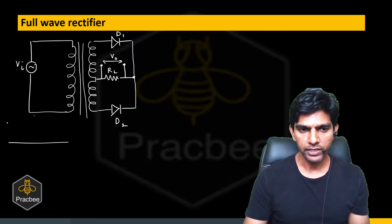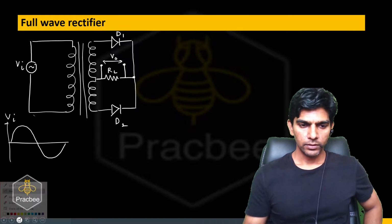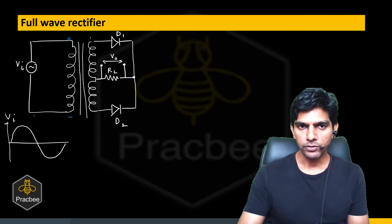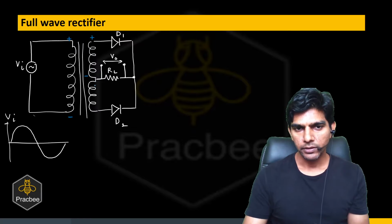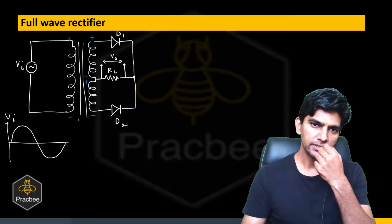Again, here what is happening? So we have a sinusoidally varying input voltage. This is input voltage, and in the positive half cycle, the top side of the primary will be at high potential and the bottom will be at low potential. Similarly, we can say the top side of the secondary will be high potential. Now it is made up of two parts. So for the first part, the bottom side will be at low, and again for the bottom half, the top will be at high and the bottom will be at low. So can you see what is happening here?